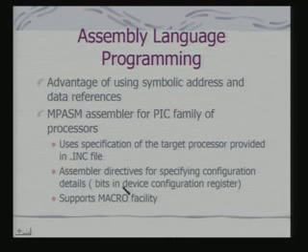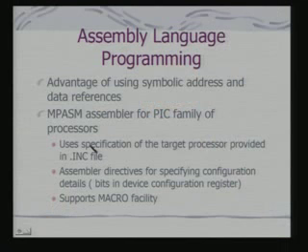Also, there is a device configuration register. The device configuration register programs your processor in a variety of ways, and this configuration information is also to be provided. In fact, these two features are nothing exceptional for PIC, because when you use assemblers for a family of processors with various target applications, you need to provide information about the configuration of the processor and specification of the target processor for assembling or translation of this code.